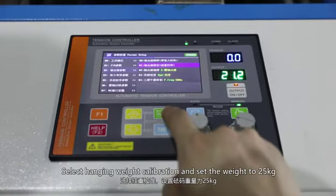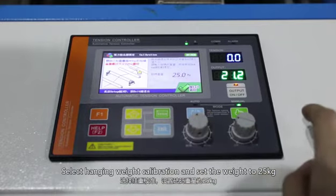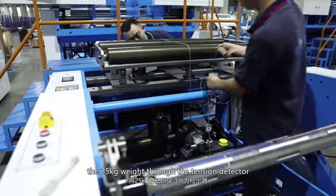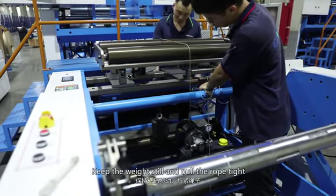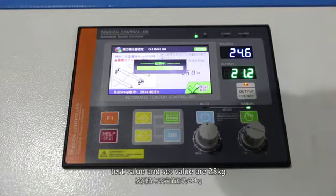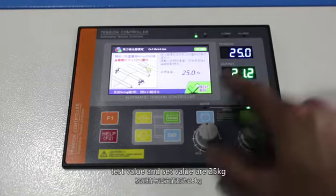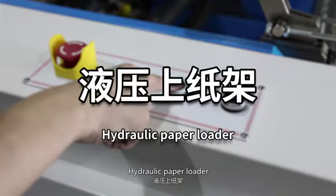Select Hanging Weight Calibration and set the weight to 25 kilograms. The 25 kilogram weight through the tension detector. Keep the weight still and pull the rope tight. Long press setup. Text value and set value are both 25 kilograms. The setting of automatic tension system is completed.